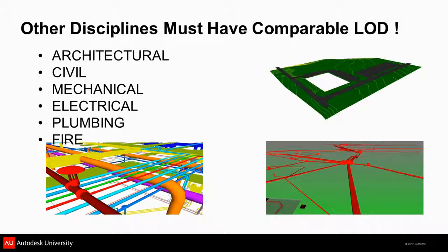What I'd submit to you is that architecture and structure are doing a dance early in design that has to get honed in. Your columns have to quit moving, and your floor-to-floors have to get honed in. One of the things I'm going to talk about is the early definition of space, but until those two are honed in, I don't think it makes sense to try to dial in ductwork, plumbing, and electrical. You need to know the overall space you need, but it's hard to dial those in if your structure's still moving.